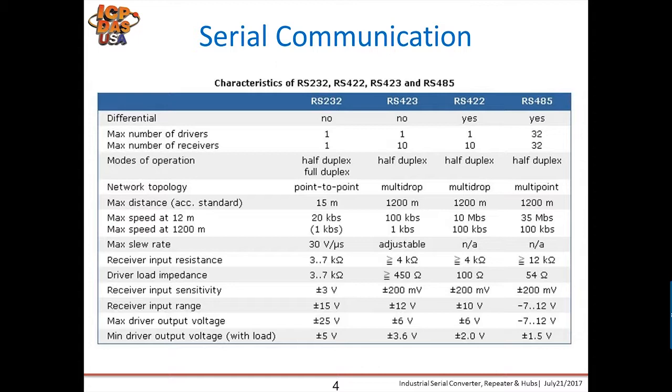For example, the IEEE 488 specifications for parallel communication state that the cabling between equipment cannot be more than 20 meters total, and no more than 2 meters between any two devices. Serial communication can extend as much as 1,200 meters.